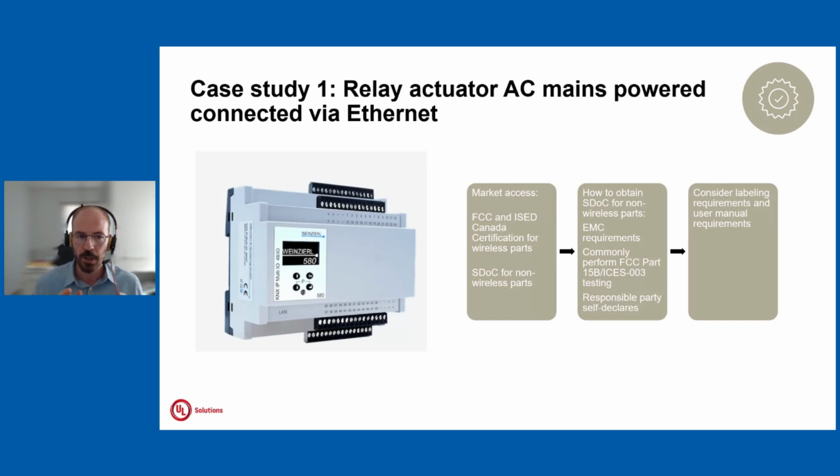Instead, when it comes to FCC and Industry Canada, we are only testing emissions. So FCC and Industry Canada only have requirements for emissions, which are radiated emissions at the enclosure, and then conducted emissions. Also, another thing to consider is that in conducted emissions, we are only looking into everything that can be at a certain stage connected to the AC mains.